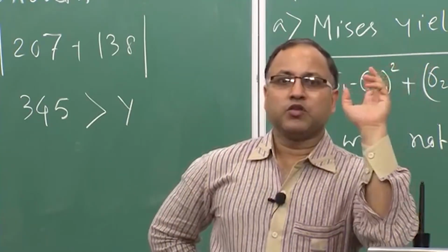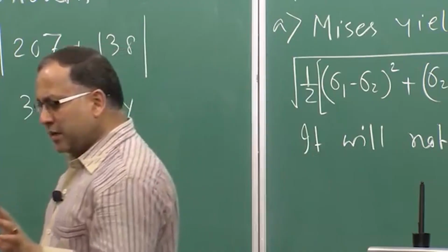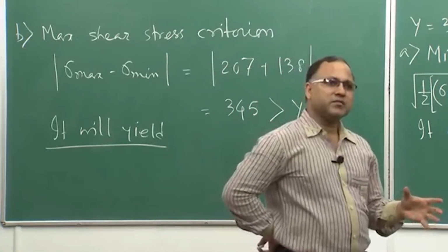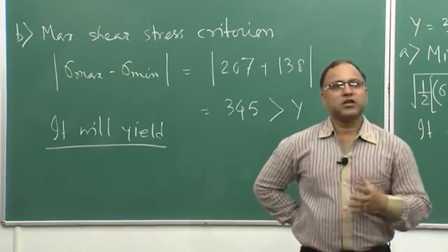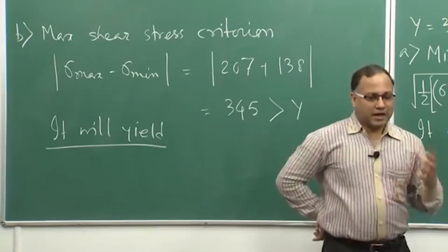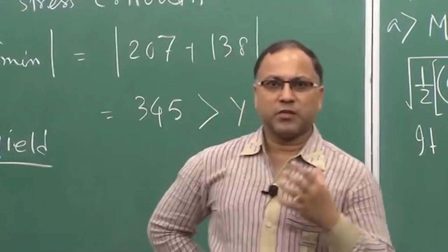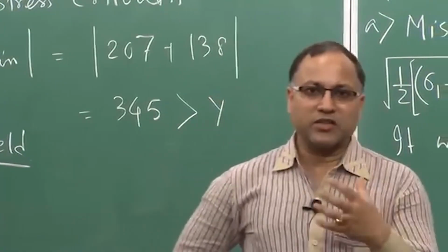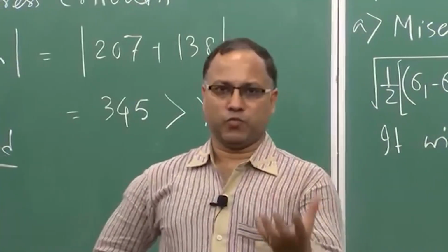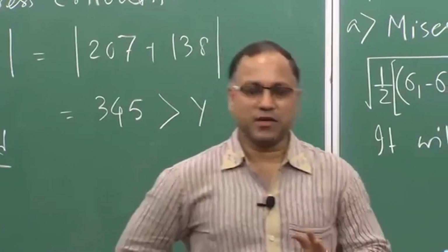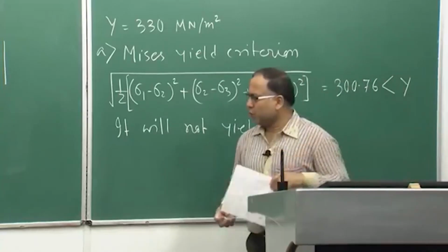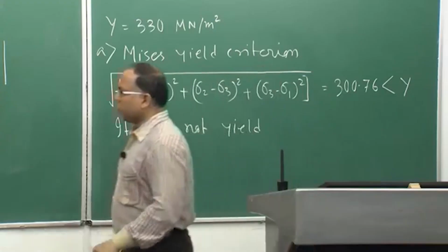So, you will get the stress developed due to the mechanical strain and the stress developed due to the thermal strain, and these two stress components must be added algebraically to get the total stress developed in the components. Okay. So, this is the idea. So, let us see how we can solve it. First we will draw the figure.